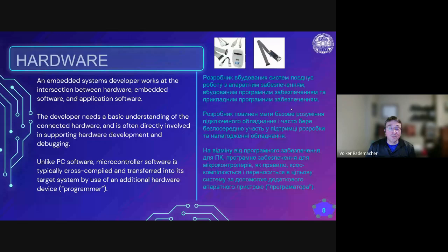Then the firmware designer will have to advise the hardware developer which processor pins are suitable for the task. You might need to prototype the circuit yourself first to make sure that it actually works before telling the hardware designer that he can go ahead with using those pins.